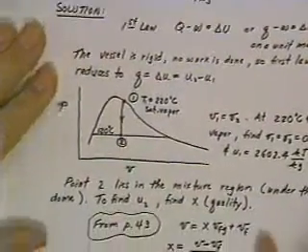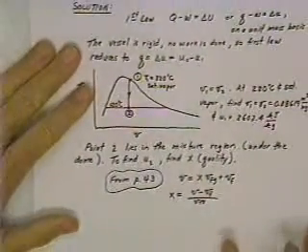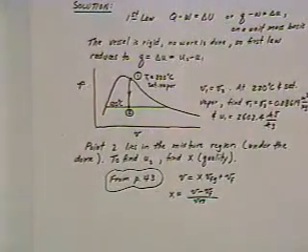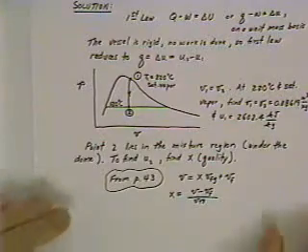All right, so if we go back now, we calculate the X. Knowing X, we calculate that from V equal to VF plus X times VFG. We have that information now that we've just pulled off the steam tables.